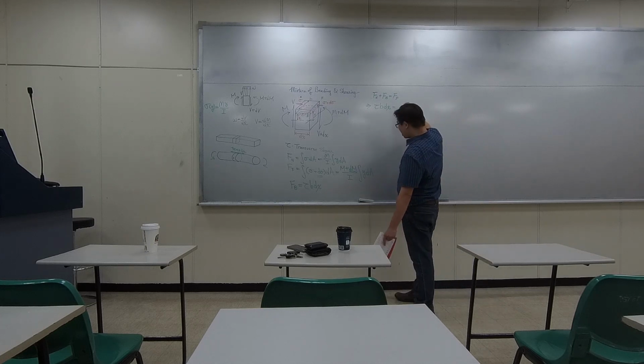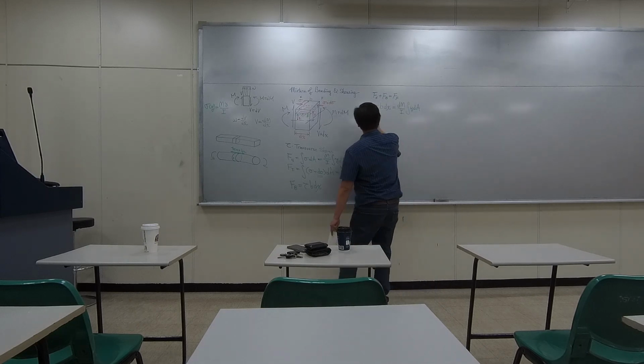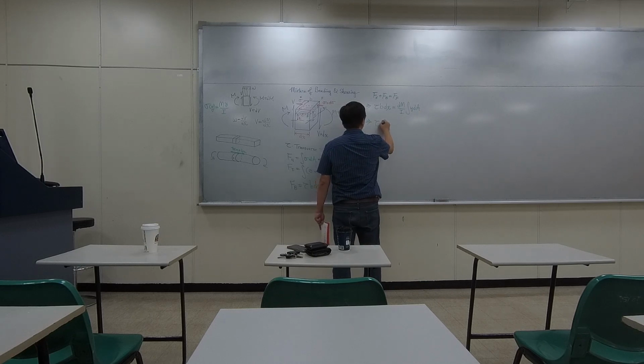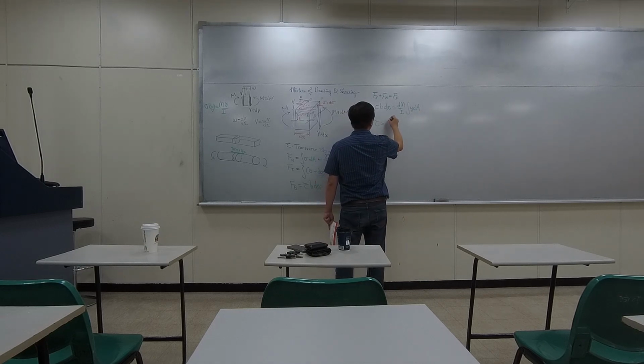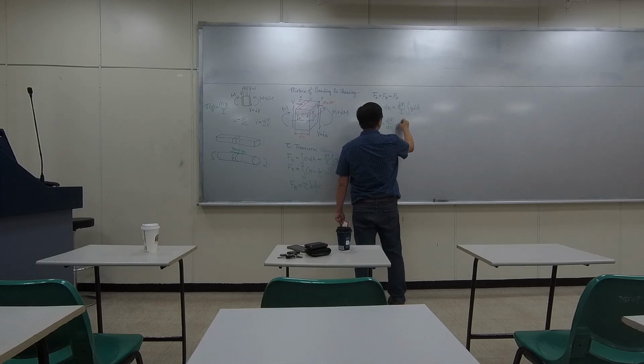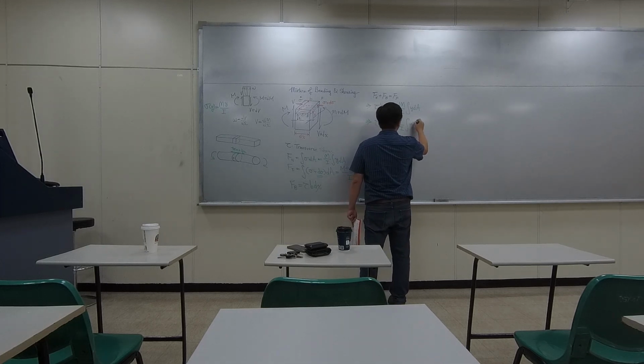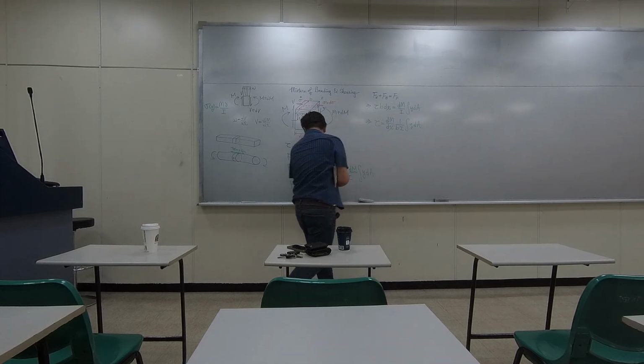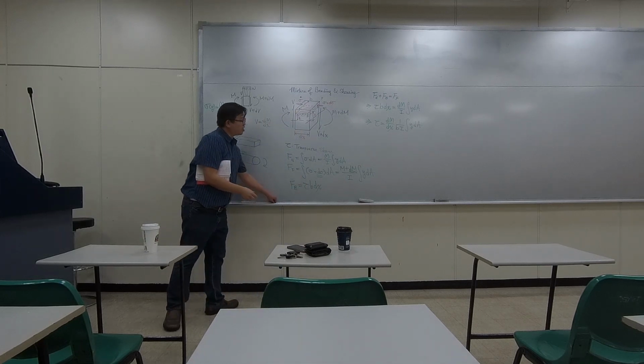So the remaining term will be dM over I, and then integral y dA. So from here you can tell tau can be computed. It's actually dM over dx, and then b multiplied I right here, and then integral y dA. Okay? That's the general equation.